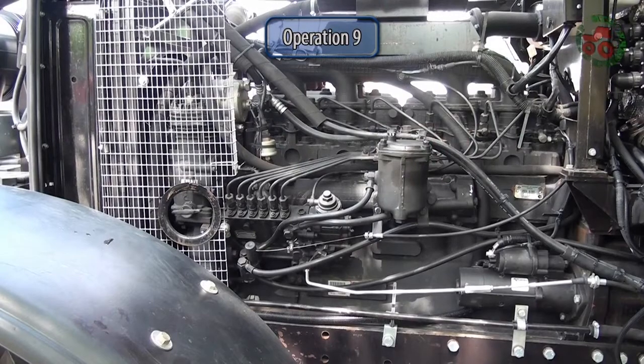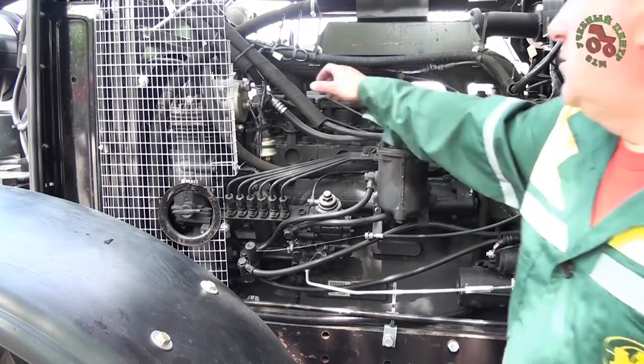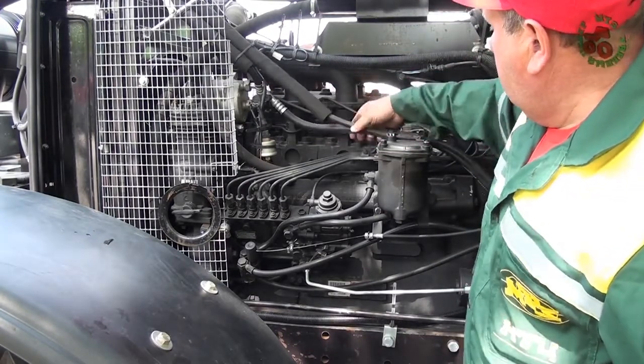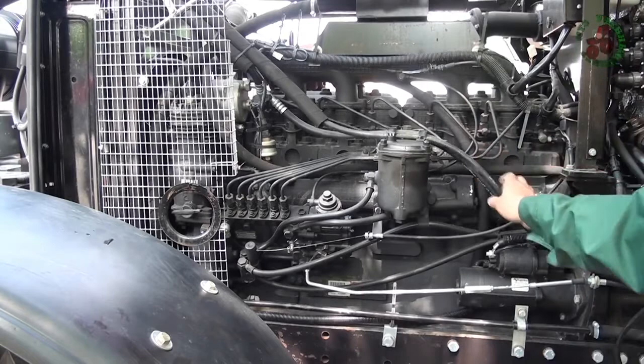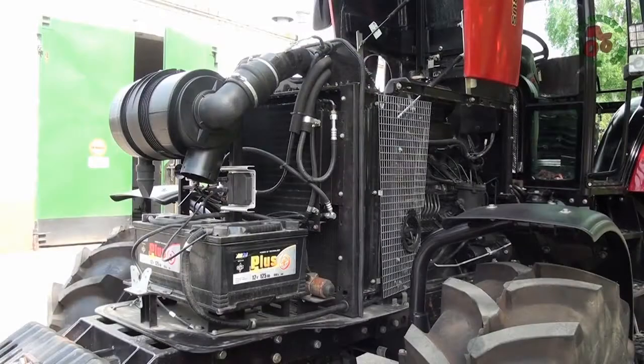Operation 9. Check air conditioner hose fixtures. Carry out visual inspection of air conditioner hose fixtures. Air conditioner hoses shall be fixed properly with coupling bands. The hoses shall not be in contact with moving parts of the tractor.